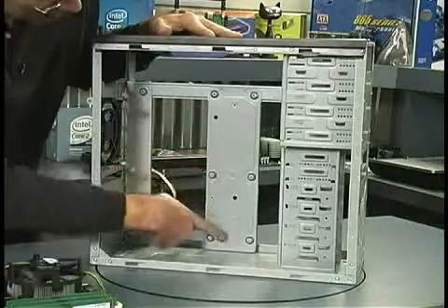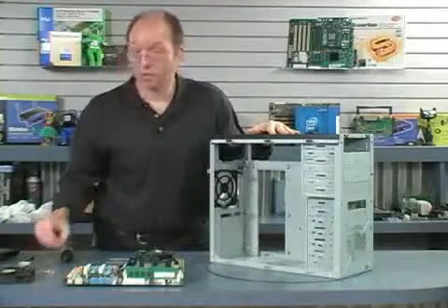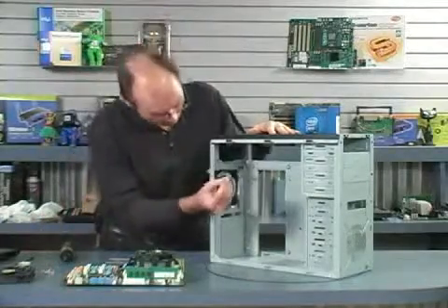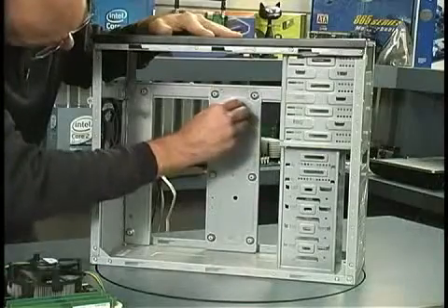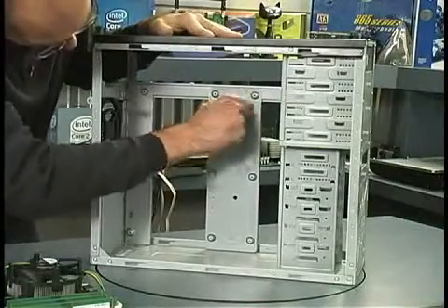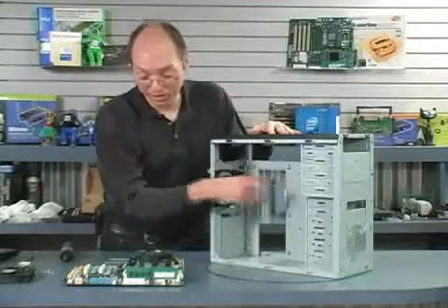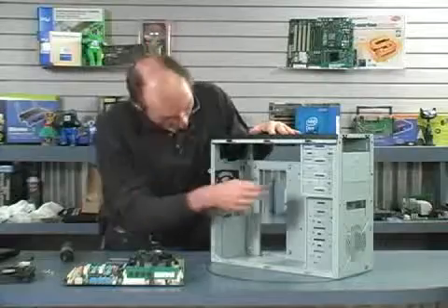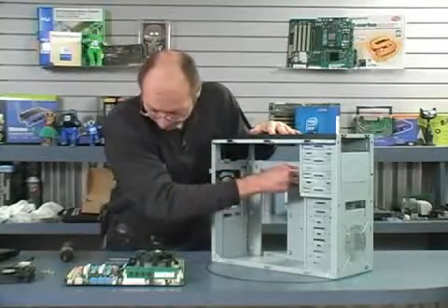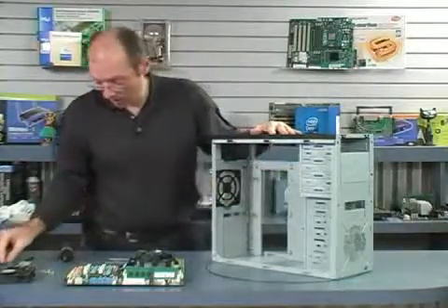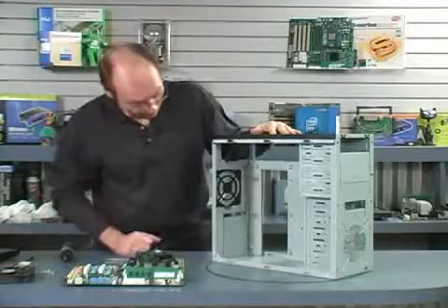You'll notice some extra drilled holes here, and usually the little bag of screws that come with the motherboard will provide extra standoffs like this one that you can screw in if you need the support in those areas. Make sure that they match the holes in the motherboard. In this case, the existing 9 holes are exactly what's correct for this board.